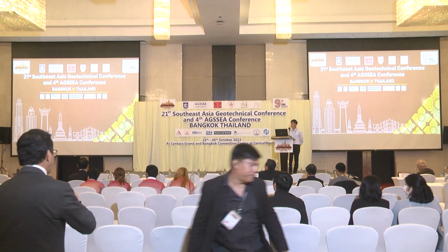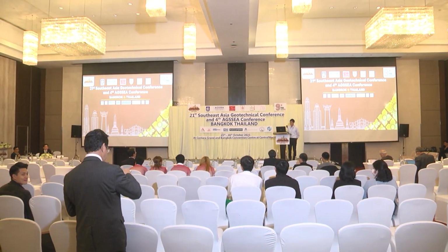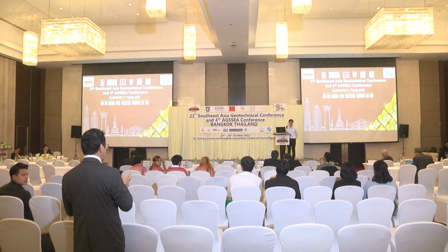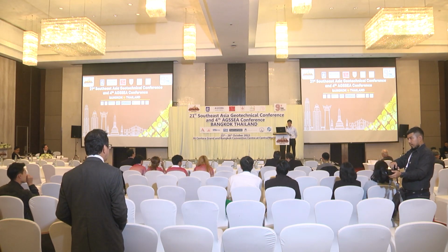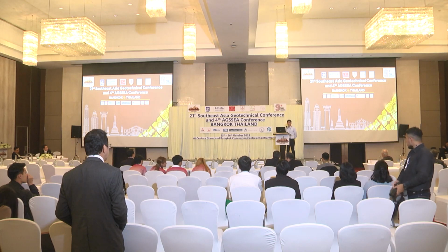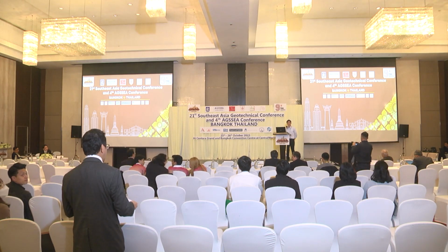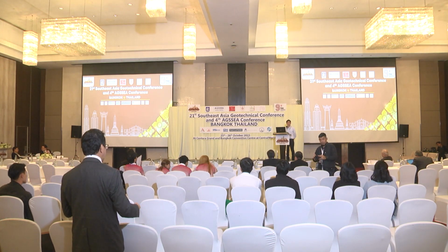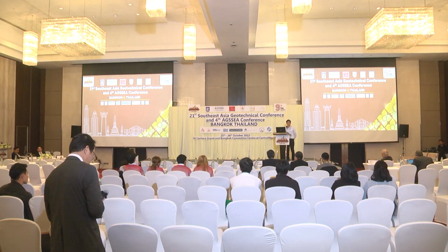Very interesting topic. See, two big professors are interested in your presentation. Just curious about your triaxial test. What kind of shearing mode did you apply, drained or undrained? In the triaxial test, it is an unsaturated condition and drained condition. So you shear at a slow rate, right? Yes, slowly. Okay, so you get the effective strength parameters at the end. It's a slow rate, right? Yeah. Okay, thank you very much.